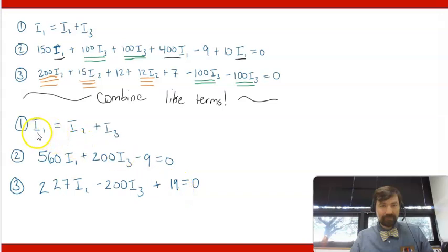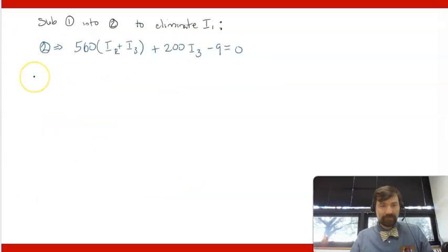And this allowed me to clean up my equations a bit so that I just see my 3 unknowns in symbolic form, I1, I2, and I3, and then in non-symbolic form everything else. So now I could go and solve the system for a final value. I basically subbed in equation 1 for equation 2 to get rid of the I1 term that was previously here.